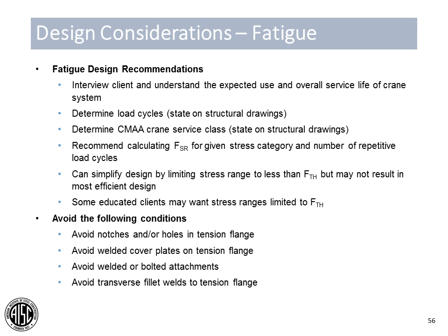Some recommendations for fatigue design. Talk to your client. We've discussed this before, but make sure you understand the expected use and the service life of the crane system. Understand the total number of load cycles, get an accurate number of load cycles that will be used, and state the CMAA service class on your drawings.